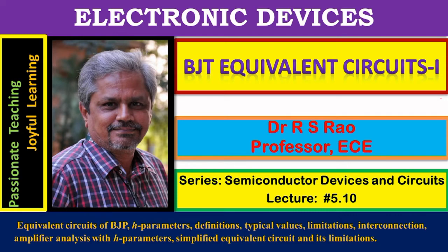Several types of equivalent circuits are available. Some are small signal equivalent circuits, some are large signal equivalent circuits, some are low frequency equivalent circuits, some are high frequency equivalent circuits, some are H parameter circuits, some are T equivalent circuits, some are pi equivalent circuits. Several different types are available for BJTs. In the present session, we consider H parameter equivalent circuits of BJT.